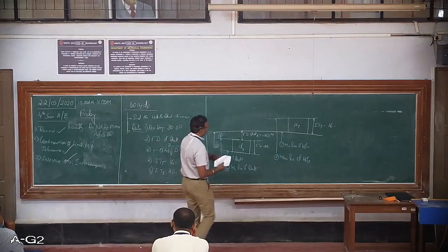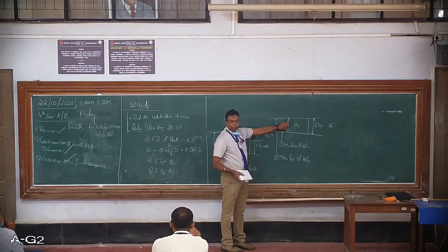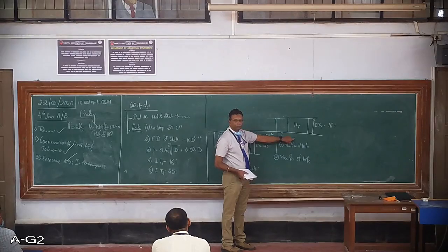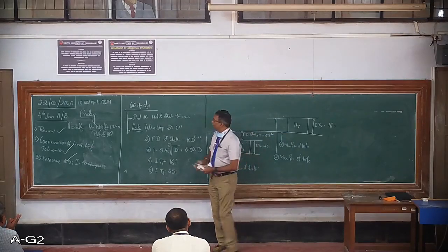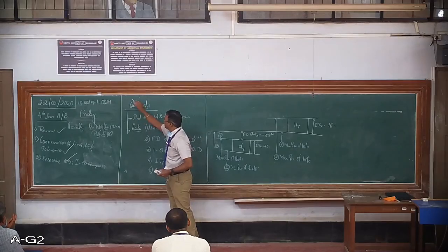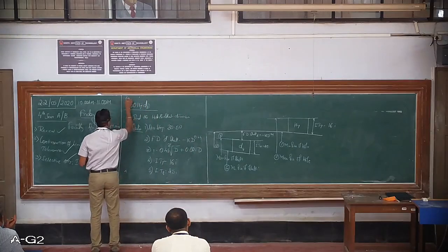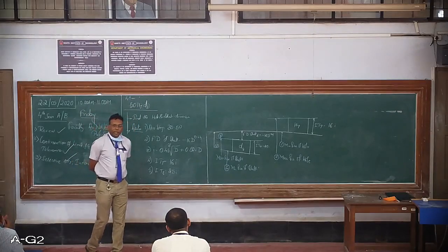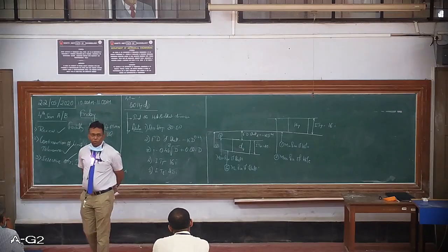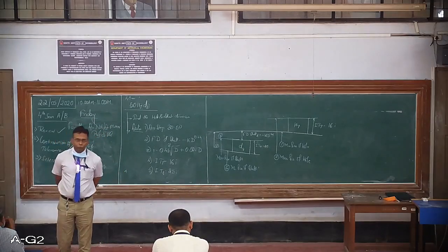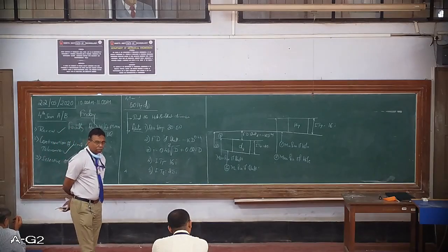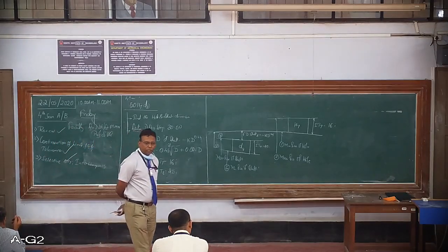Look, when you consider perspective, this is the minimum size of the hole, in the sense that a hole manufactured below this line, below nominal size. Say if it is 50 mm, if we make a hole of 49 mm, two questions. One, can it be accepted? Obviously not. It is not adhering to the standards. It should be 50 mm H7. Fine, it gets rejected.